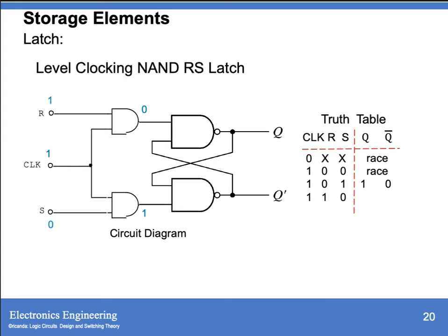Then if we have 1, 0, so your second AND gate is 0 and your first AND gate is 1. Then if it is 0, remember in your NAND, if we have 0 as one of its inputs, then it will generate an output of 1. 1 NAND with 1 is equal to 0. So therefore your Q is 0 and 1 for your Q bar.